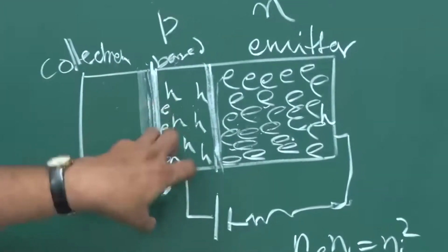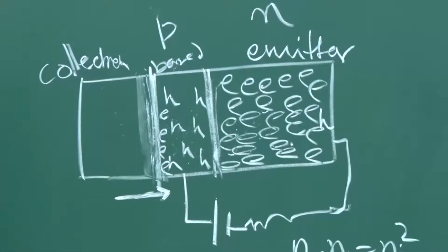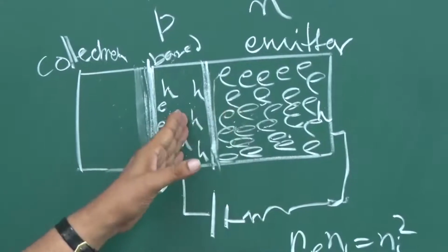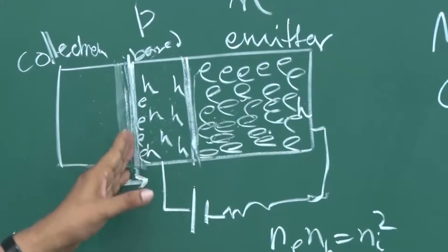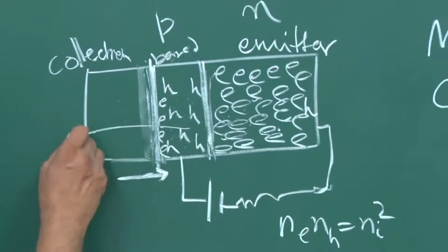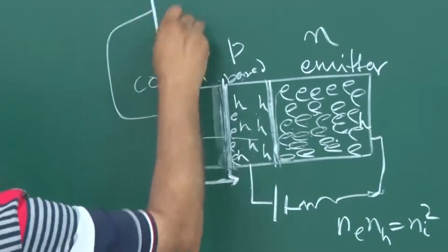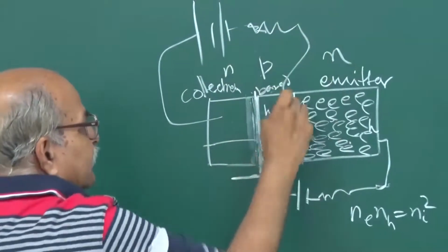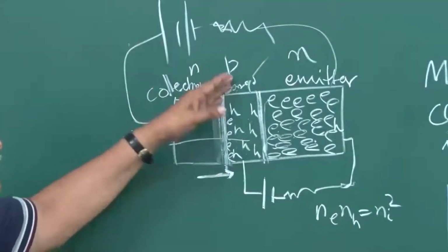This electric field helps the minority carriers in making the reverse current, and therefore all these electrons reaching this depletion layer, where you have this field, will be drawn towards the collector and will go to the biasing battery. This is P, this is N, so you should have positive here, whatever resistances and all that. It's connected here, but anyway, the potential difference is there.